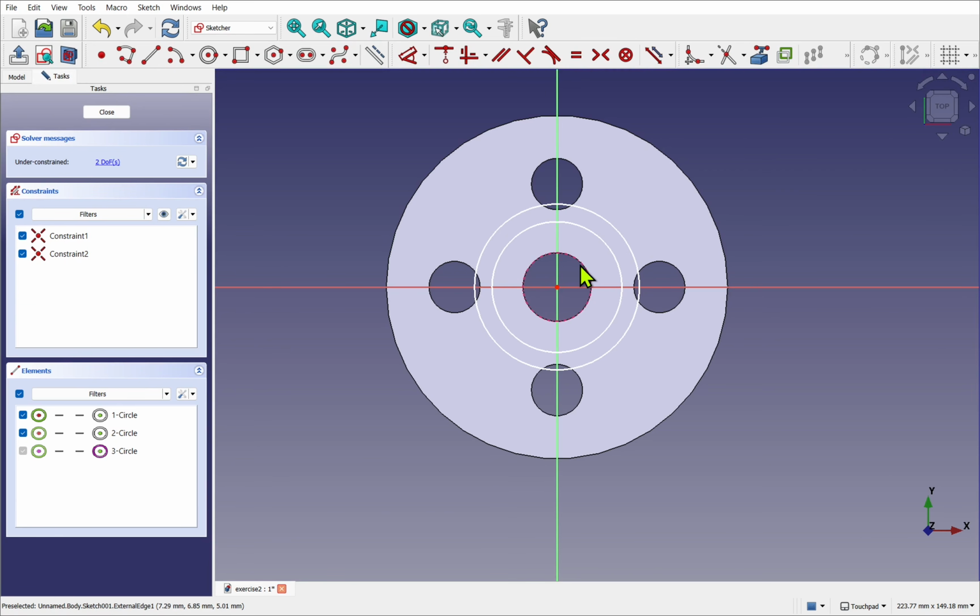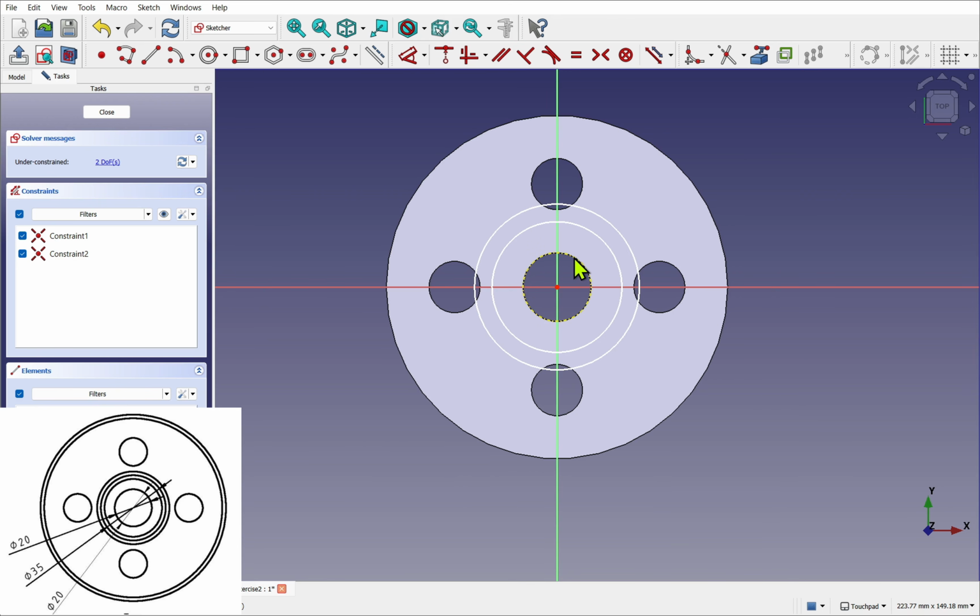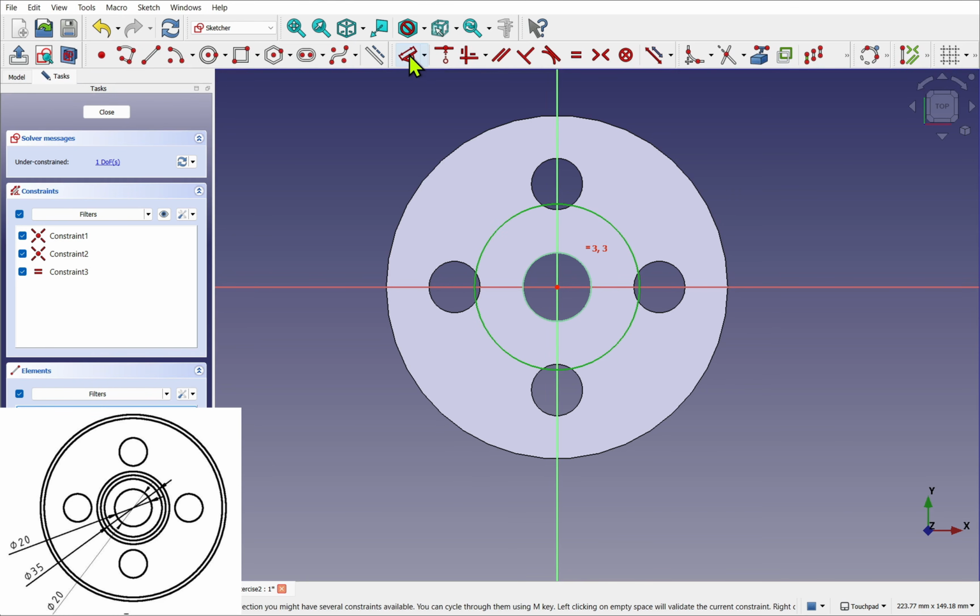This geometry won't appear if we close the sketch, but what we can do with it is now select it and say select the circle and make those equal. This saves us adding a datum constraint and will also mean that if the underlying feature changes, so will the geometry in the sketch. So now let's select the circle and add a diameter using a dimensioning constraint.